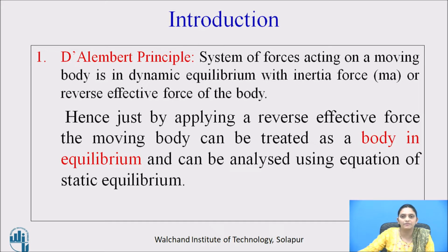D'Alembert's principle states that the system of forces acting on a moving body is in dynamic equilibrium with the inertia force, or reverse effective force, of the body. Hence, just by applying a reverse effective force, the moving body can be treated as a body in equilibrium and can be analyzed using the equations of static equilibrium.